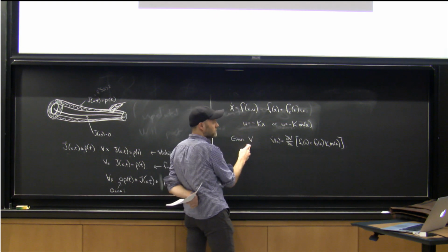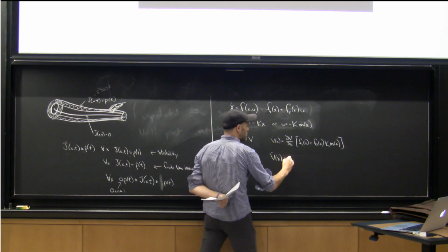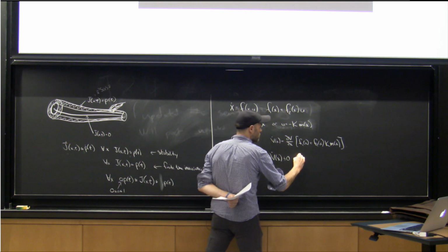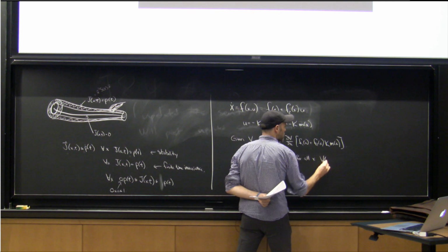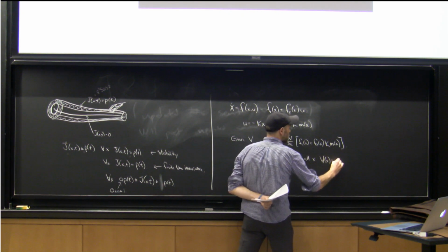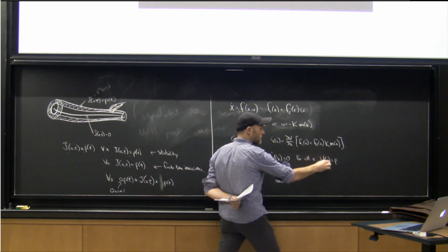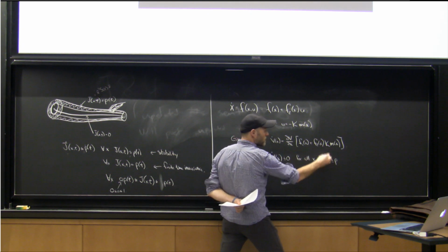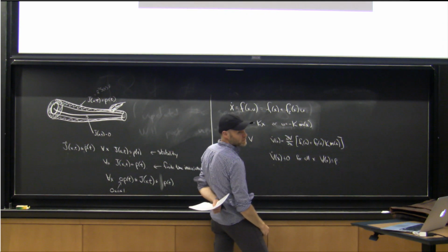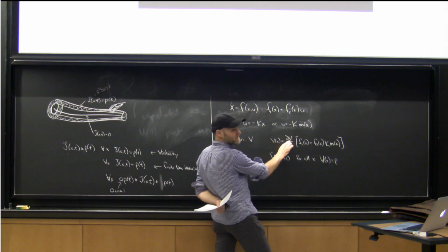V is given, then the search for V dot of x less than 0, for all x where V of x less than or equal to rho, is actually still, if I lock in rho, it's still convex in K. Okay, so I can actually use sums of squares to search for rho and K simultaneously. What I can't do is search for K and V simultaneously.